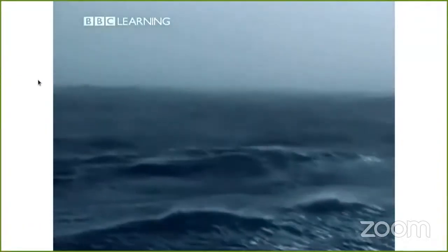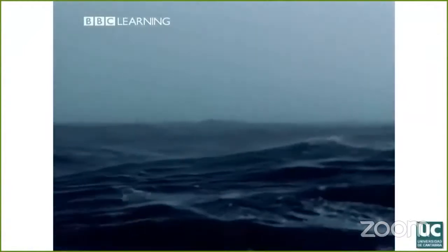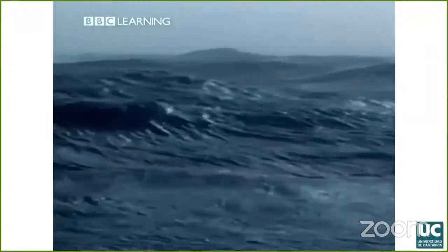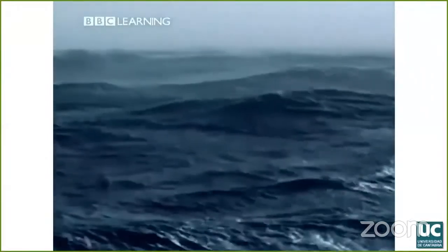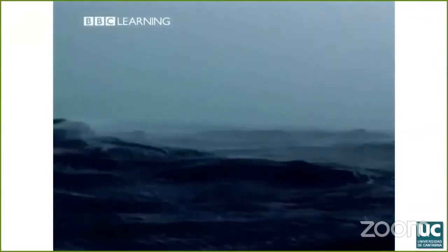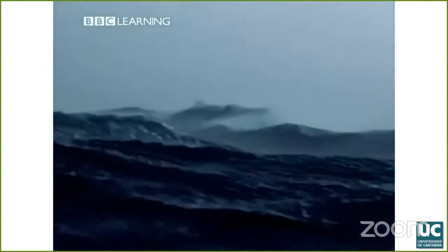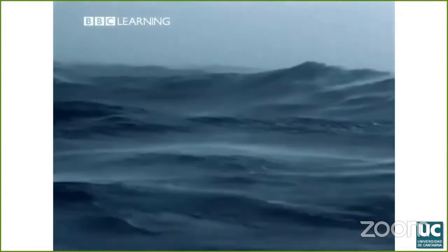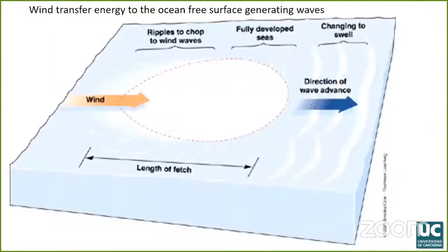To study the behavior and characteristics of ocean surface oscillations, we usually analyze them by means of mathematical models that describe homogeneous properties of the energy in the ocean in the time domain, frequency domain, or statistical domain. The interval of time in which we can assume that the energy of the free surface oscillation at a particular location of the ocean is constant is defined as a sea state.